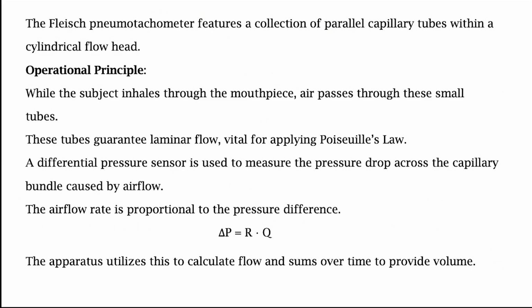In these cases, you can use modern manufacturing methods, 3D printing, photolithography, and you can create really small tubes. Now, what is the size of the tube? In the order of micrometers. Remember, micrometer means then what will be the capital R in that case? You need to compute, no? Modern manufacturing methods, for example, photolithography, allow radii in the order of micrometers, and tolerances that are extraordinarily good.